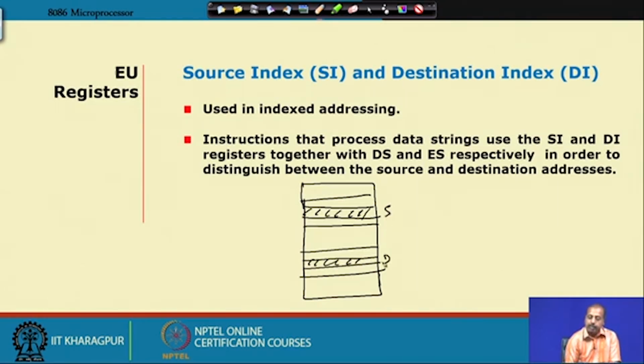There will be a number of bytes that you want to transfer. So, what you can do is initialize this segment register to point to DS, this segment register to point to ES, then the SI register you initialize here and the DI register you initialize here, and you can initialize another register, CX, the count register, to hold the number of bytes that you want to transfer.